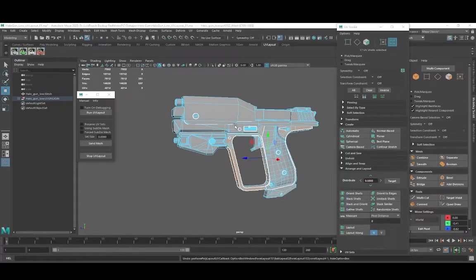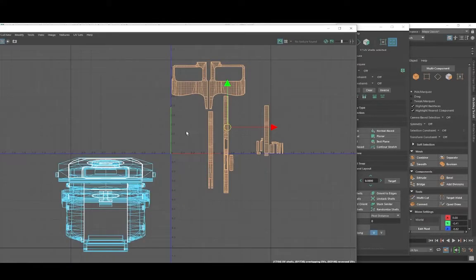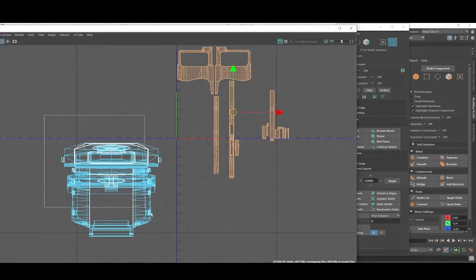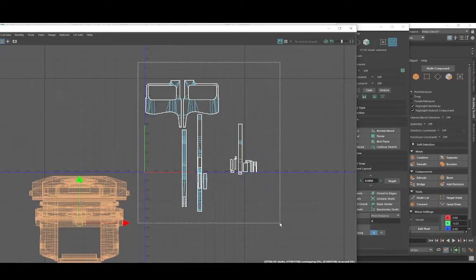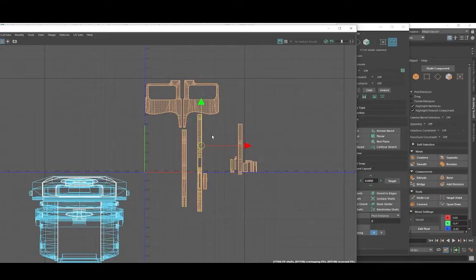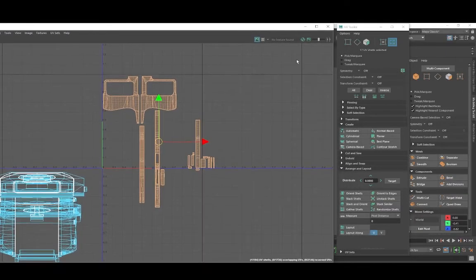We are back in Maya, and I'm going to bring up the UV space so you can see that we have sent the Headus UV Layout to Maya. These pieces are the meshes that we didn't unwrap, and these are the objects that we already unwrapped. So when you have everything unwrapped in your model, you can pack it.